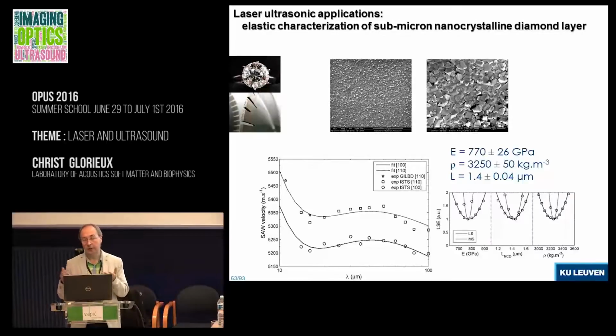And as we know, one of the challenges in microelectronics is to get rid of the heat, because the frequencies are high and the power consumption is too high. So you want to evacuate the heat, and then in the end you want to cool it. So diamond could potentially be a layer used for heat extraction. Diamond is a bit slow to make, so typically the layers are very thin. In this research we investigated how well diamond can help to evacuate the heat.